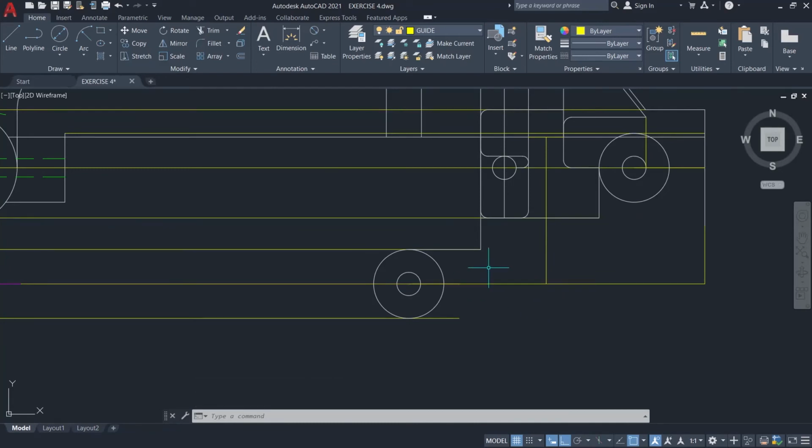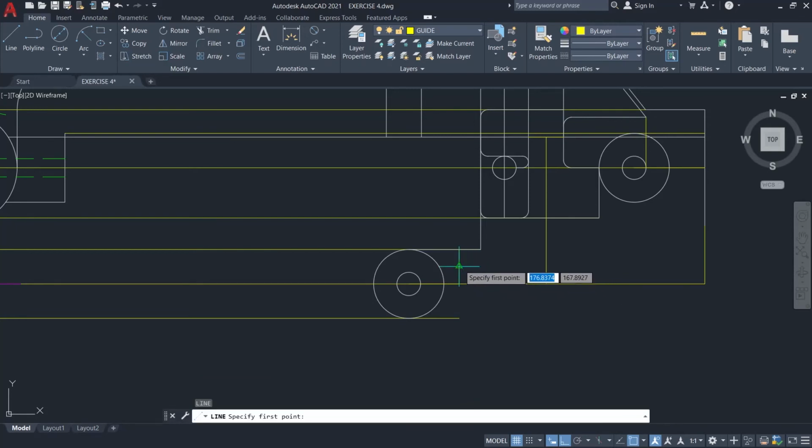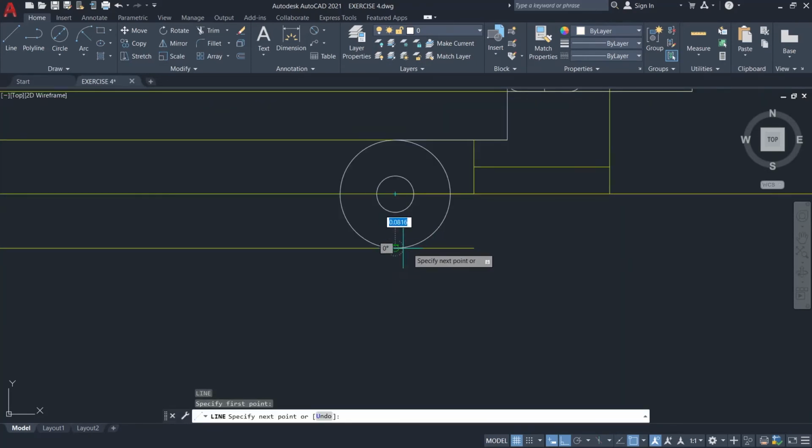While from the endpoint of our 9th set of guidelines we made earlier, create a line upward until it reaches this line. From its midpoint, make another line until it touches this vertical line. Before we proceed in making those curved lines, from the bottom part of the larger circle, make a line measuring 0.80 units.